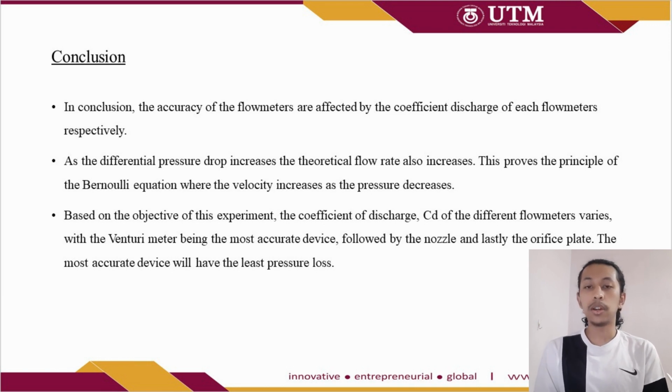And based on the objective of this experiment, the coefficient of discharge CD of the different flow meters varies, with the venturimeter being the most accurate, followed by the nozzle, and lastly the orifice plate. And the most accurate device will have the least pressure loss.